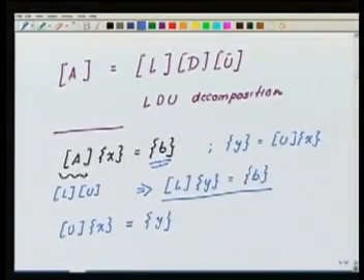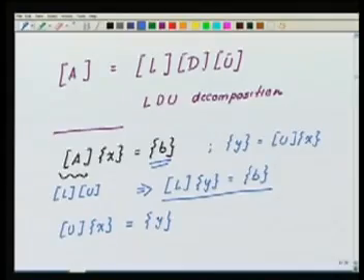Okay. Now this makes life very simple because if I have a stiffness matrix, and I want to change the loads applied on the structure keeping the boundary conditions and the material fixed, then my stiffness matrix is going to remain the same. Now as the load is changing, my load vector, which will be this side, is going to change. When the load vector changes, then I do not have to do a Gauss elimination on A all the time. I can have the L and U in store and simply take the new load vector, operate on it with the L and U, and I get a solution. So that is something we would like to have.